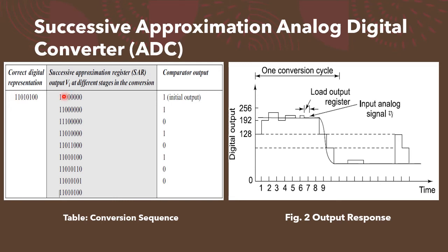Here this digital is converted into analog, and now we are getting that this value is greater, since this is 1101, this is greater. So if VA is greater, then automatically the next bit will be 1 and the remaining are 0. Now these two are compared. And when these two are compared, this will be greater. And so again the next bit will be 1, the remaining are 0.